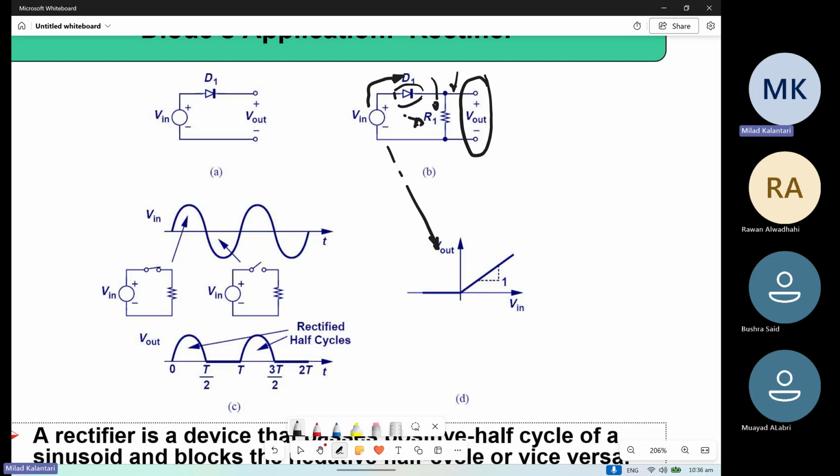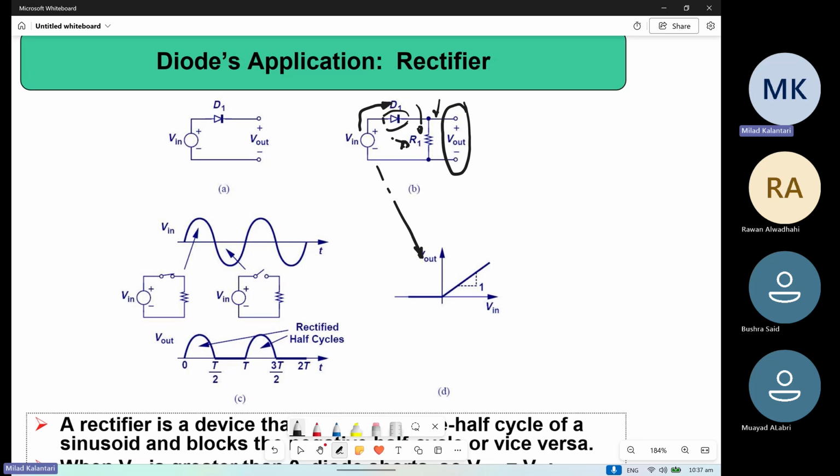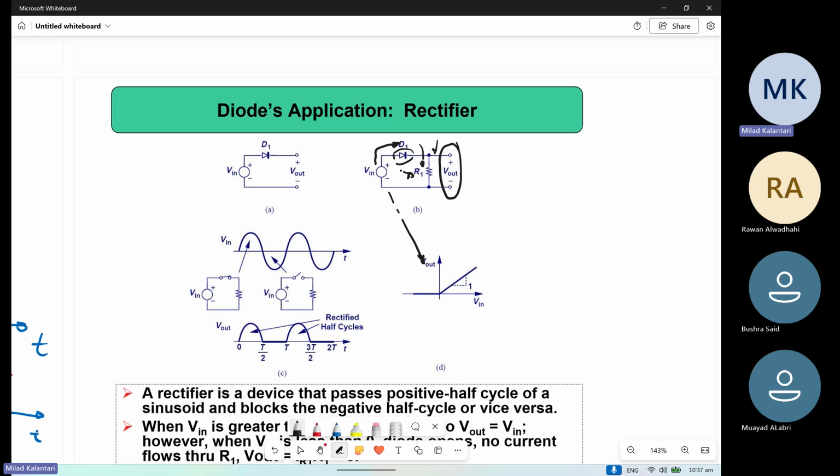So it doesn't waste the current of the supply. If you want to make your rectifier more efficient with less power consumption, you should avoid that kind of wasting current. So this one has less waste. People usually make the rectifier like this rather than the other one, though both circuits have the same kind of rectifying characteristics.